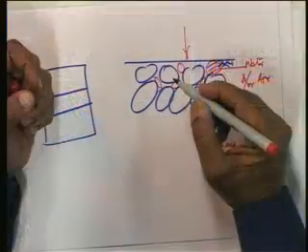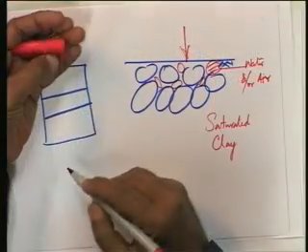Suppose we look at this movement and readjustment of the solids, when would they take place? They can possibly take place only if water which is inside is expelled. Why? Because the water which is inside the void space is also incompressible. So, imagine we are applying a load here.